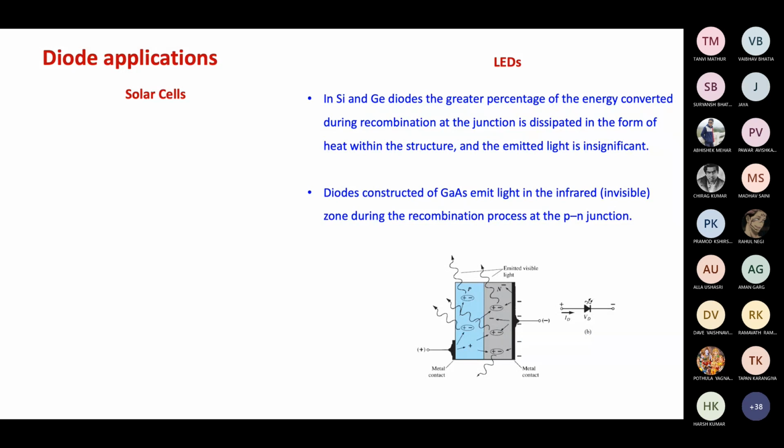But apart from that, as soon as an electron hole pair is created, we can try to separate it, and we can try to have a better solar cell. The basic principle of a solar cell is that we have n-type material, p-type material, and the depletion region in this material. The structure is shown in this way so that one of these is small. For example, the p region is small here, so that the light can go up to the depletion region and create electron hole pairs at the junction.